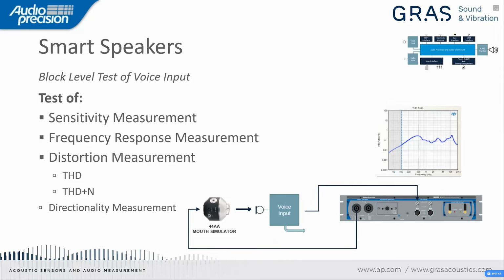Another important measurement we're doing in this configuration is a directivity measurement of the voice input of our microphone array, because it is very important when you have a smart speaker that it's not depending on where you are standing in front of the speaker before it will react.